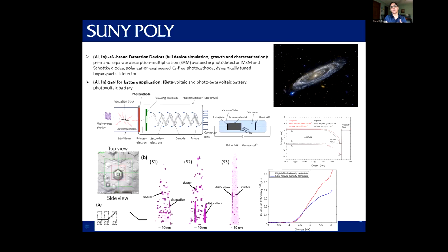The band diagram shows that by doing band engineering in the III-nitrides, we create a system where the conduction band falls below the vacuum level at the surface, so the created electron by photon absorption can be extracted out of the system.